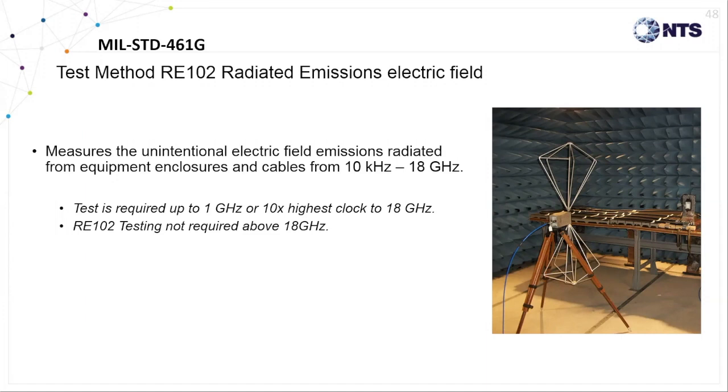RE102 doesn't require testing above 18 gig at this time. However, it is common to see test requirements beyond 18 gig, for example, up to 40 gig for special projects or space applications where high frequency communication signaling is used.